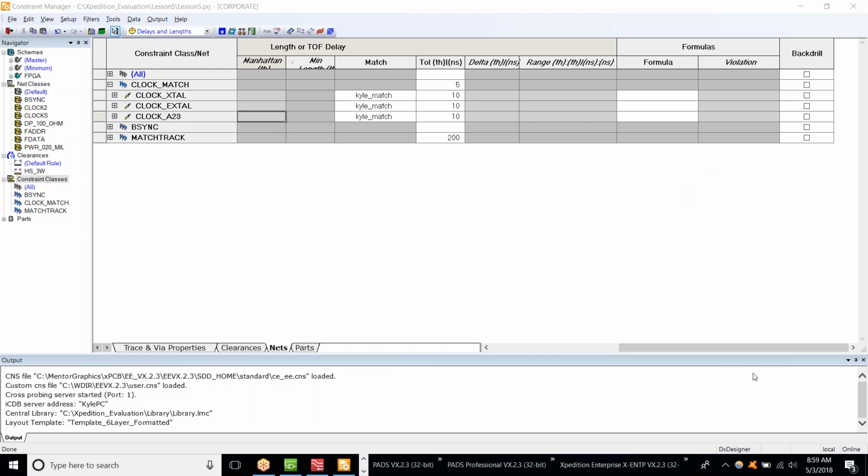Hi, Alan, I see your question here, and it looks like you're asking, do you have a means to account for length / time internal to the part? So like a package delay. Not really. You can get that from the data sheet most likely. That should be on there, and we can definitely account for that within the Constraint Manager if you bring that in. But no, just from creating a cell in the layout tool, it doesn't automatically create a package delay. That's really based on the internal packaging design and the internal design of that IC you're working with. So you'd have to account for that from the data sheet and then go ahead and account for that while you're entering the constraints.